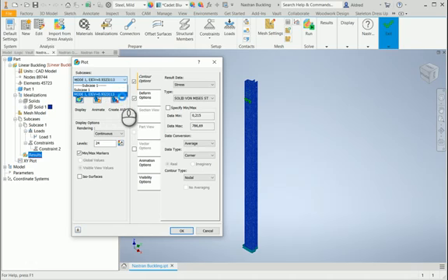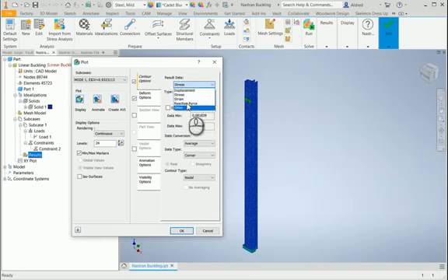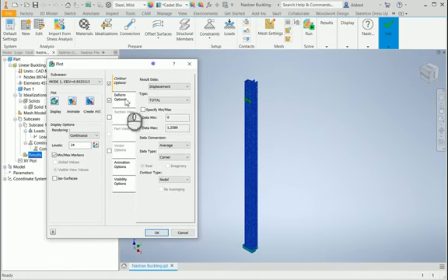If you want to look at the mode of when it's buckling, select mode case 1, and under result data, we can go to displacement. From displacement, we can take a look at the display, and it'll give you a visual representation of the mode of the profile buckling.